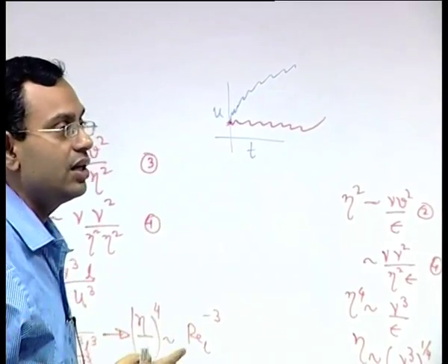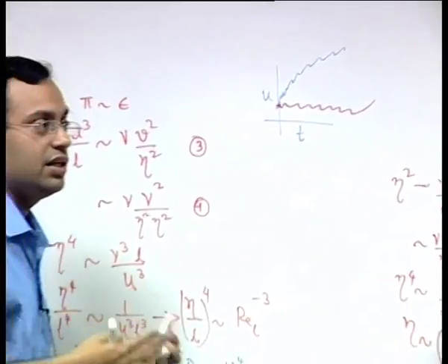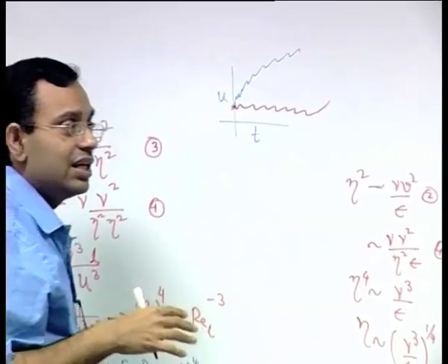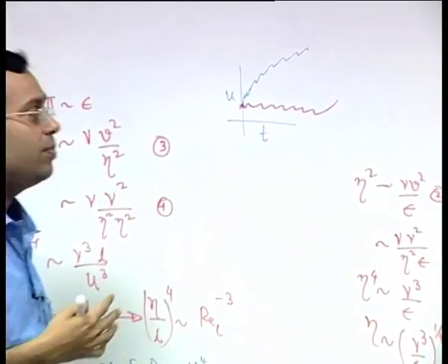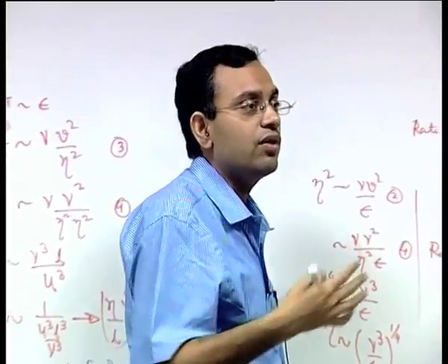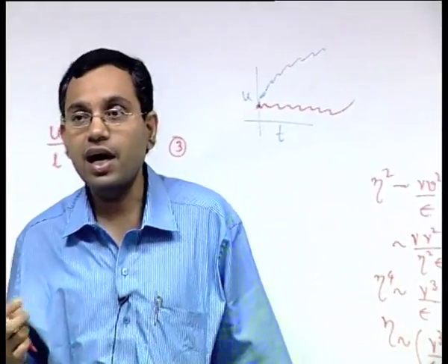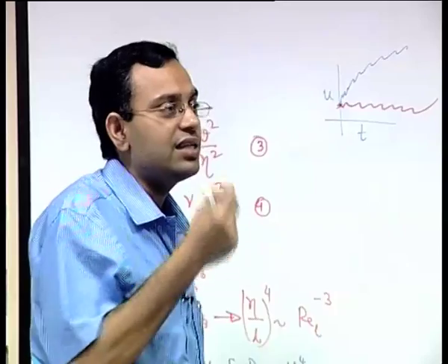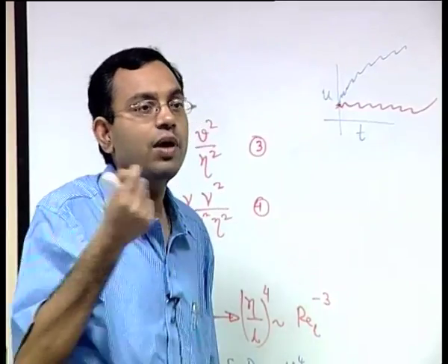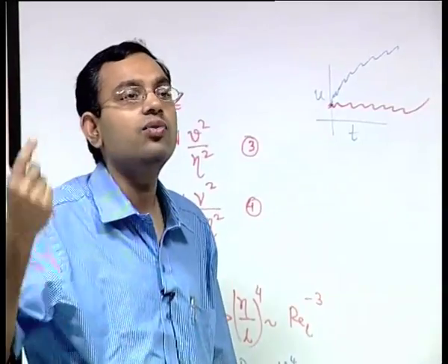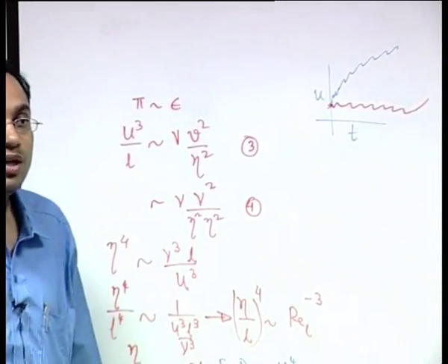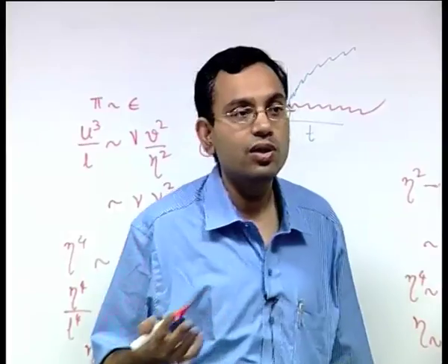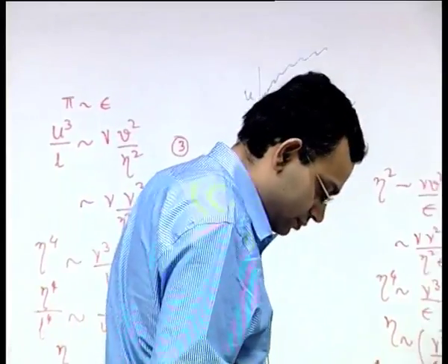We will see later what role vorticity plays in the dynamics of turbulent flows, but what we can see here is that this highly sensitive dependence on initial condition is also one of the hallmarks of turbulent flow, and that is why it is very difficult to model numerically, because a slight numerical perturbation may entirely lead to a different solution. So dealing with the actual instantaneous quantities in turbulent flow is not a very easy thing.